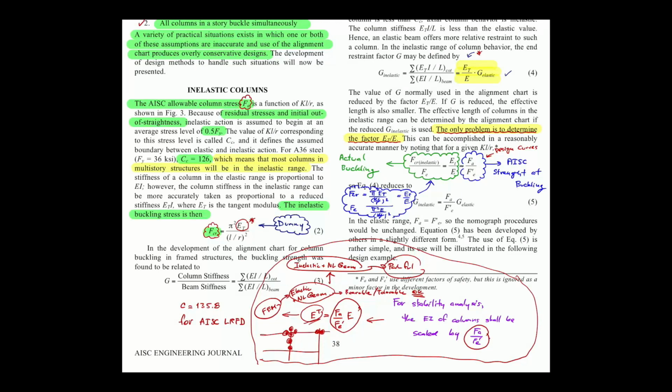You can modify the tangent stiffness, so you change the elastic modulus of steel from E to ET using these modified values, and then run an elastic nonlinear geometry analysis, and keep iterating until you get good convergence.